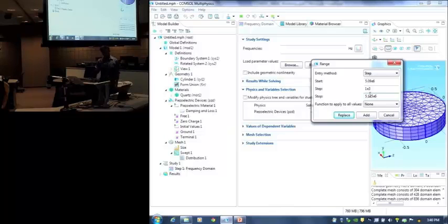If you really have no idea what eigenfrequency you want to look at, you can't get these numbers right away. It's an iterative process. First thing you would have to do in this case is an eigenfrequency simulation. You do eigenfrequency simulations, and then you figure out what is the shear mode you're interested in. So you look at the plot and you see, okay, this is the shear mode that I'm looking for. Once you know the shear mode you're looking for, you get the eigenfrequency.